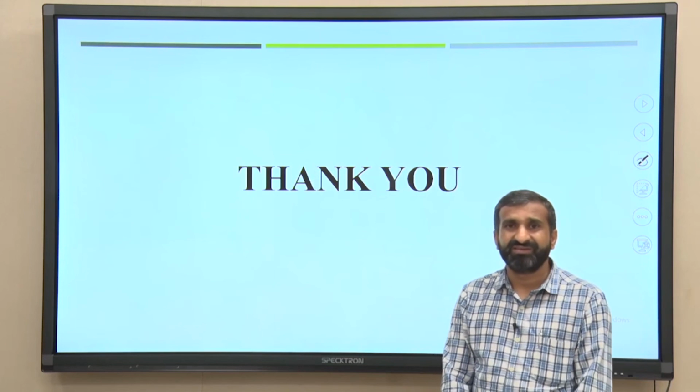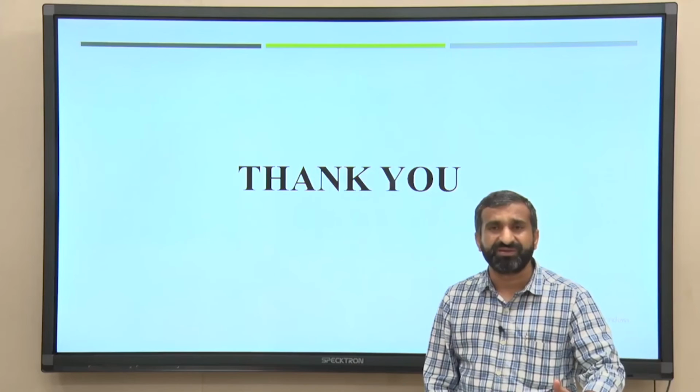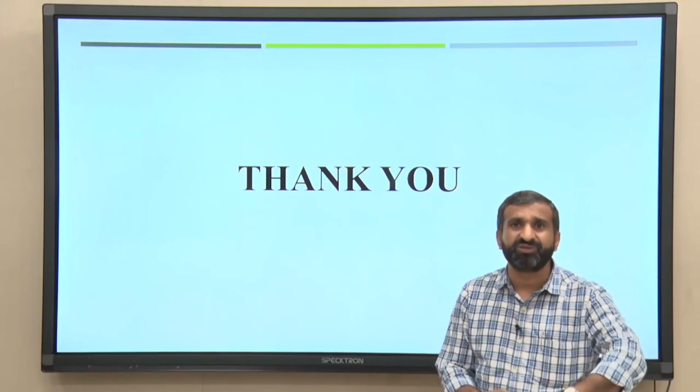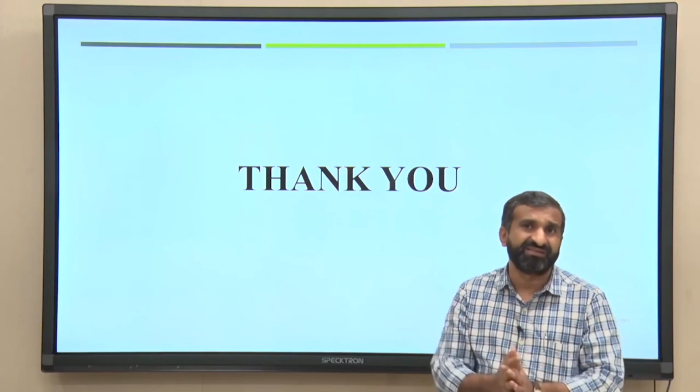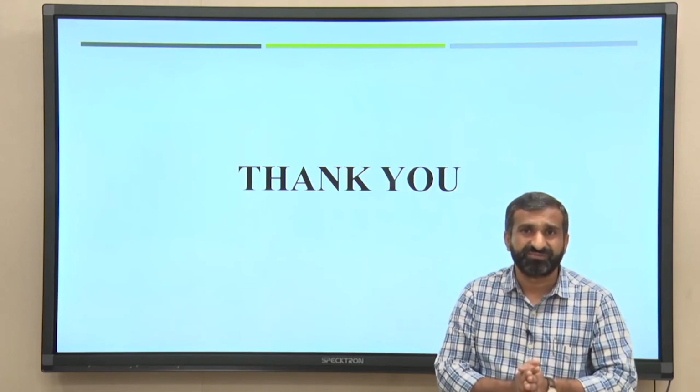So, thank you. I hope you have understood very well the different stages of the anaerobic digestion process, and also that there are different factors affecting biogas production or methane production. So, thank you.